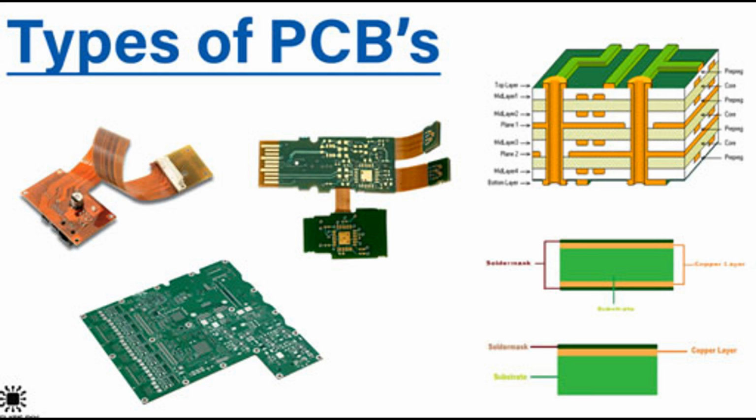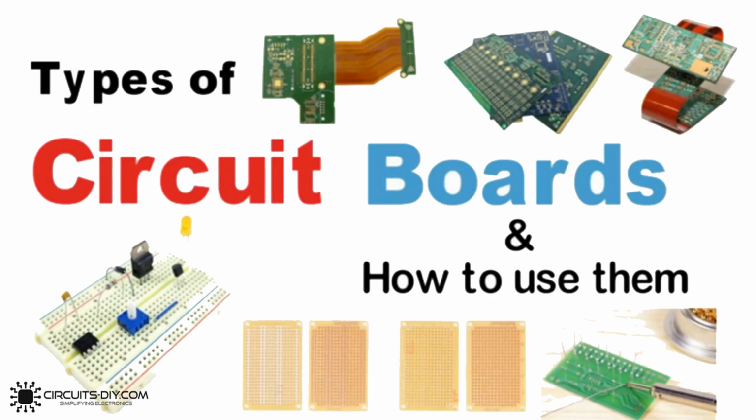Design considerations. Size. The size of vias, including their diameter and annular ring, the copper pad surrounding the via, is determined by the PCB design requirements, such as current carrying capacity and the spacing between traces and components. Placement. The placement of vias is critical to achieving efficient signal routing and thermal management. Designers must carefully plan via locations to optimize the PCB's performance. Annular ring. The annular ring is the copper area around the via's hole. It should be large enough to ensure a robust connection but not so large that it interferes with adjacent traces or components.